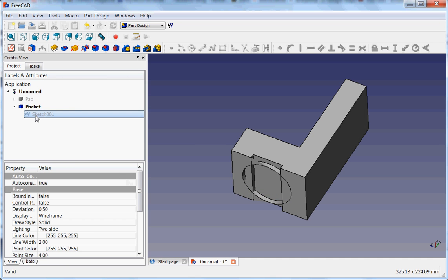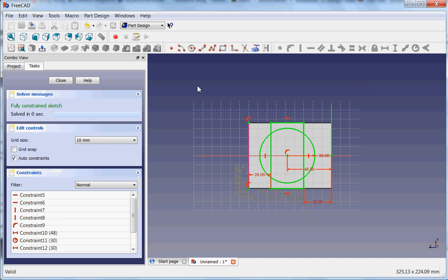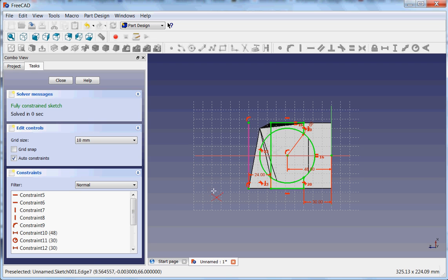So just go here, double select. So it is only one shape and not two intersecting shapes that we have here like now. There's quite an easy way of doing it, and that is this tool called trim. And that is going to cut a piece of the circle between these two lines. So if you do it like this, and then like this, and then like this.